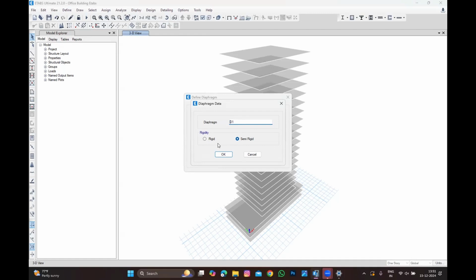From beam to column. When there is high seismic, the beam top reinforcement, they will embed it into the columns. Now what you're doing, you are only stopping on top of the column, as an L bar, only for LD. You need to take it further for the high seismic zone. The detailing is entirely different. Then it will be considered as fully rigid.